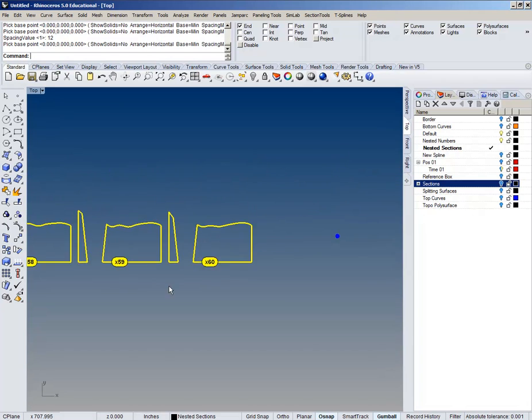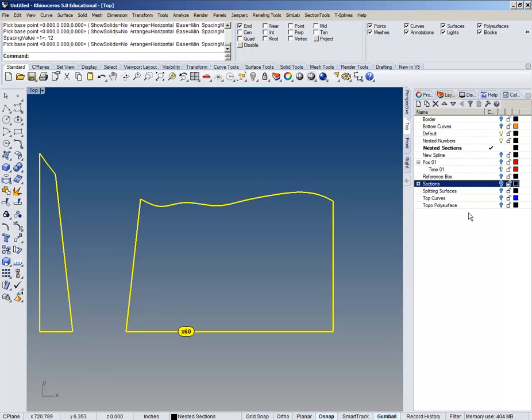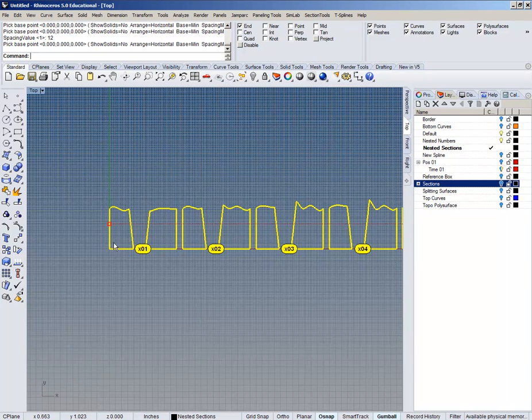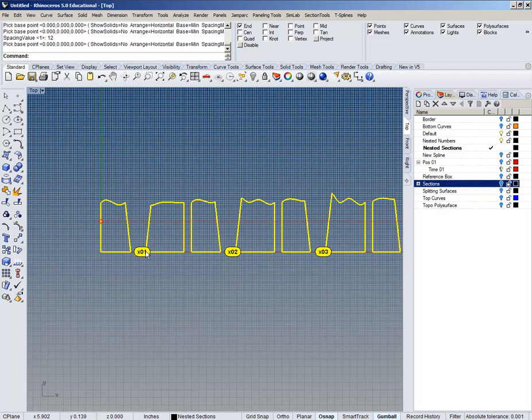So I'm in pretty good shape. You can see that this is actually a section here. It just gets really tight all the way up there. So these annotation dots are not great for laser cutting because they don't transfer. They're just dots. They're good for us because no matter how I zoom in, they're always the same size. They don't take up a space. But what I really would love to have is curves, and I want the least amount of curves possible to get my information across. The problem with text is typically text conversions will give you an outline.